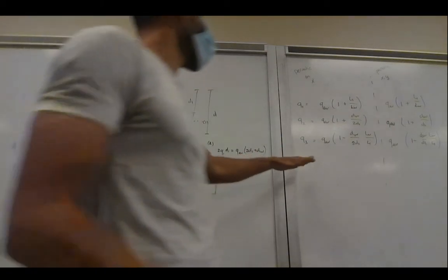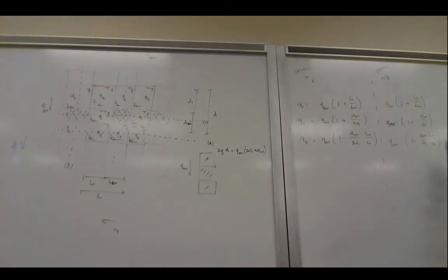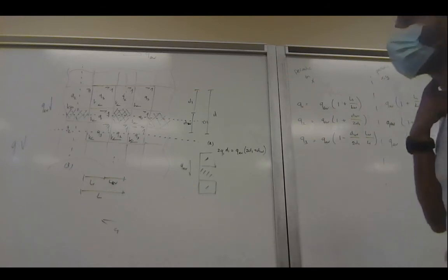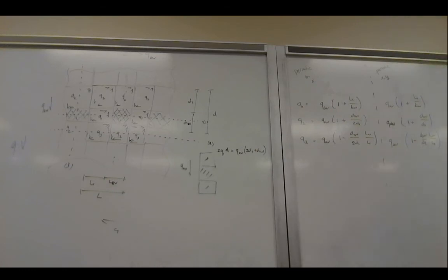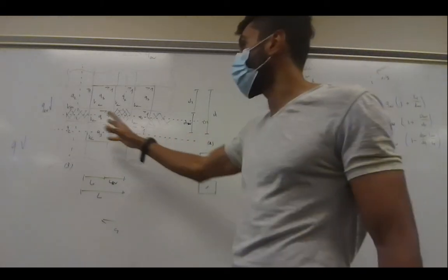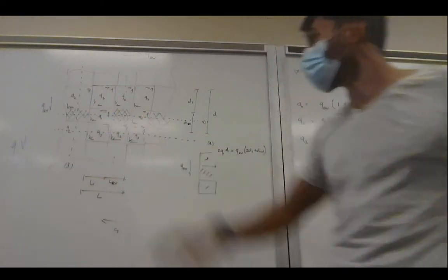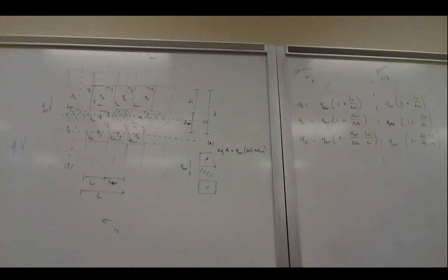So this is basically a very simple equation that we have derived and could be used every time that we have a periodic cutout. So as long as we know what our far field stresses are, we can determine very quickly what our shear flows are in the panels adjacent to the cutout. So this is again a very straightforward and simple exercise.